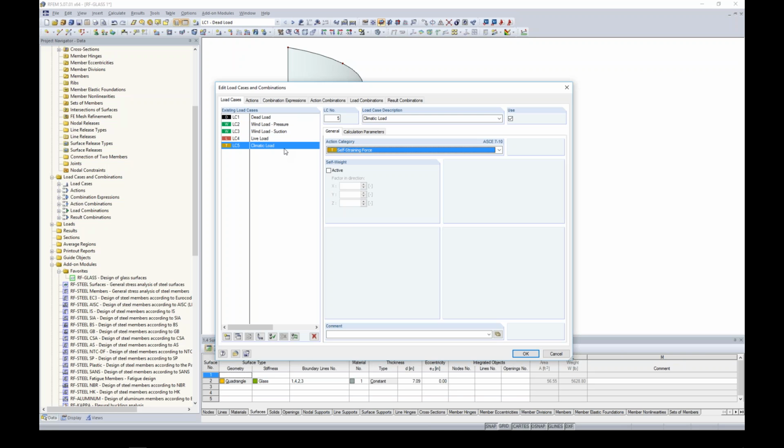You certainly can put your climatic loads into any one of these load cases that you want, but keep in mind, maybe for climatic loads you want a load factor of 1.0. When you put it in with dead load, well, now it has the same load factors as dead load. So most likely you're going to want to keep them separate from these other action categories, which is why I created climatic load. This does have a load factor in our ASCE load combinations of 1.0.